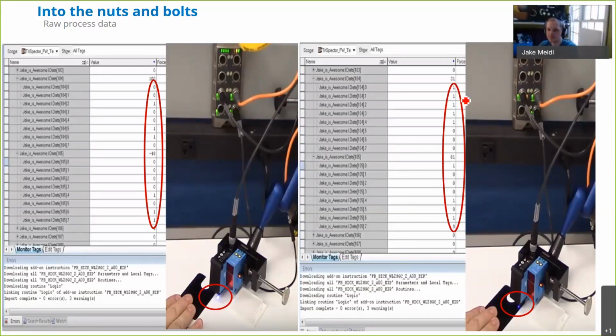All right, so here's that data map. I took a screenshot from RSLogix. We've got our 100 and minus 48. And now we'll put the KTS process data on the same screen. What are we looking at? What's going on? I've got a bunch of ones and zeros. Most of us use the calculator on the PLC or on your PC, and we'll enter a binary value, and then we'll convert it to decimal. So ones and zeros, where do I start? What do I start entering into that calculator on my PC?